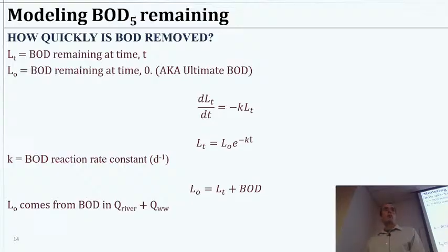And here's where I'll remind you that when we do BOD5, that's not all that could possibly ever be removed. That's just our best estimate, or a 5-day estimate. So we're getting into kind of strange waters here where we typically measure in 5 days, but this ultimate BOD would be, well, what happens if you gave it an infinite amount of time?